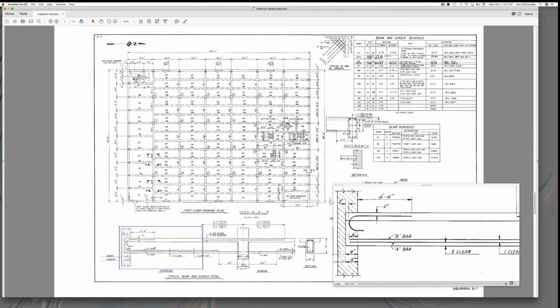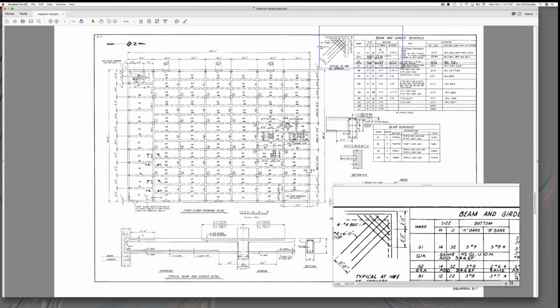confusing, I'm sure. Coming across, you start one at 2 inches, starting right here, 2 inches out. Then you have 2 at 5, so you have 5 inches and 5 inches, 2 bars. And then the rest of them are at 8 inches on center coming out across there. That's what that means. The reason they do that is they have a lot more shear stresses at the edges, where all the loads are coming in, turning direction to go down into the concrete, down into the vertical portion of the concrete, if that makes sense for you. Okay? And the girder is going to be the same way.